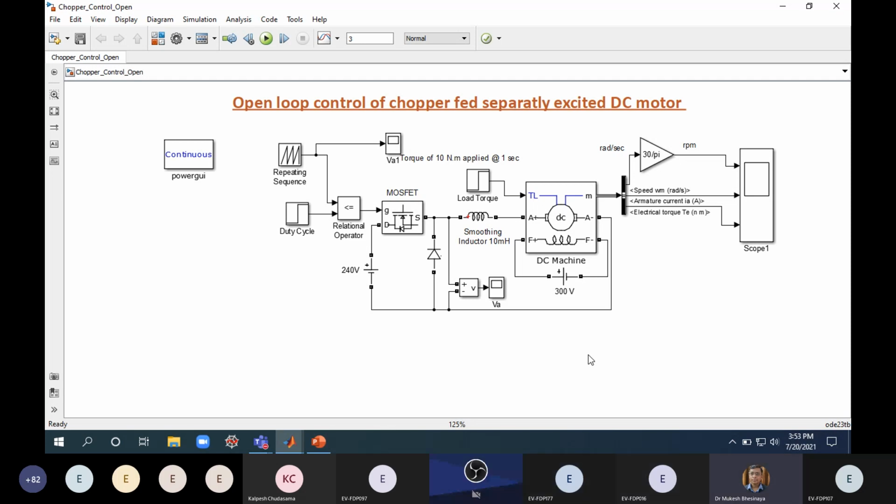What generally we have to do is provide the motoring action as well as the braking action. Regenerative braking. So you need to go for a two quadrant configuration, or a full bridge type of configuration, wherein you can achieve both these modes of operation. Or many times in some of the EVs, in one of the papers recently I've seen, 4 quadrant operations are being performed.